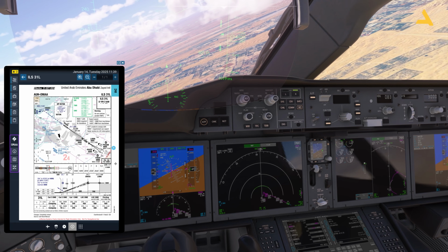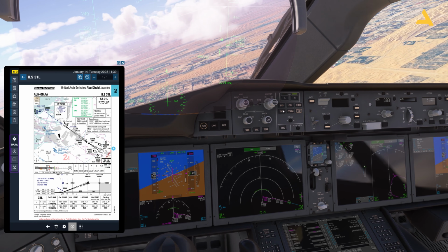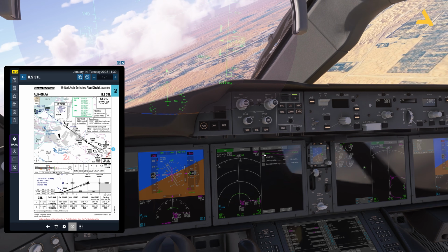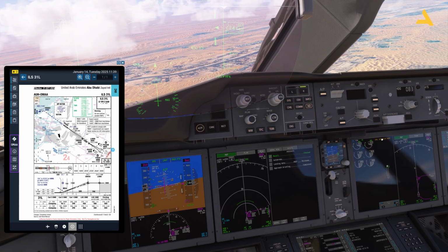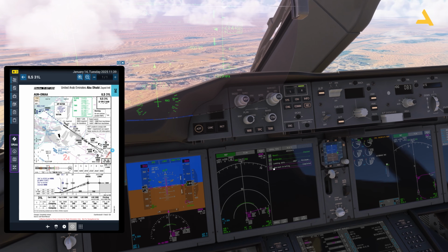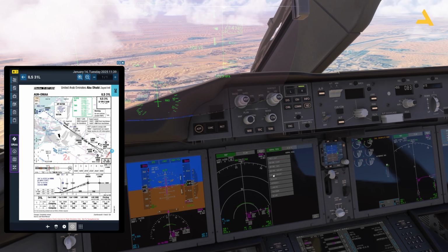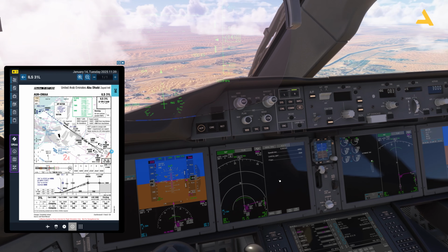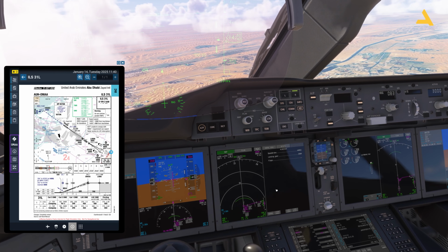Now the plane will be near Pegam soon, so let's bring the checklist. So if you press this button right, then you will see the checklist over here on the screen. For the descent, recall check, because you have to press this button to check for any issues. Checklist was incomplete. Auto brake set to maximum. Required for the landing. Landing data done. Approach briefing complete, normal. And now for the approach, altimeter set. And now for the landing, I will just keep this checklist over here to remind me if anything is left or not.